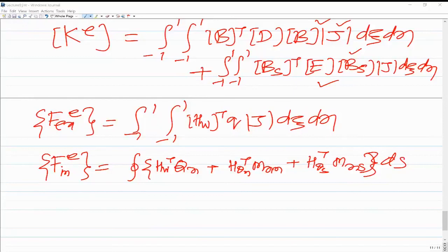Sir, so if the derivatives are involved, yeah. Okay, sir. Then can we conclude that this conversion to natural coordinates is applicable for all cases? Yeah, it is applicable to all cases, but see, the derivatives are also involved. So now the same thing, if you try to do it for the classical plate bending element, where you have primary variables as w, del w by del x and del w by del y, w as well as its derivatives, even if you formulate it, because we are already talking about that element with 3 degrees of freedom at each node, w, del w by del x and del w by del y, I talked about.